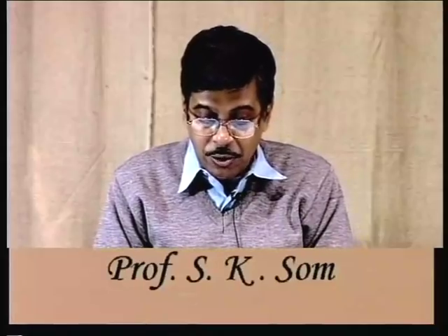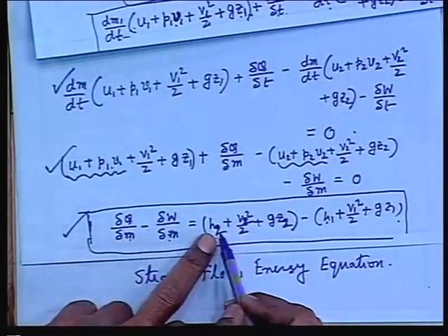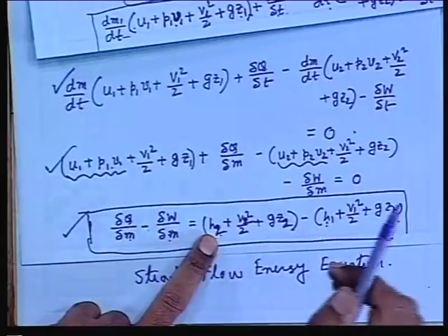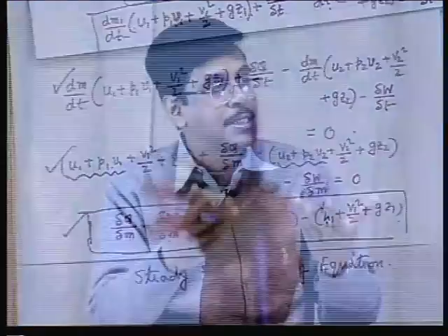In almost all the practical appliances in engineering use, the differences in kinetic energies and potential energies are negligible compared to the change in enthalpy. We are interested in these two quantities as engineers. We are interested in the changes, not the absolute value, because an engineer wants to know the work and the heat interactions, and they are always described by the first law in terms of changes of properties: changes of enthalpy, internal energy, kinetic energy, potential energy. We are not bothered about the absolute potential energy.